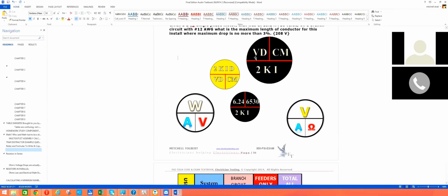But at any rate, anytime you get to plug in something for a voltage drop, either on this yellow circle or over the black circle, either one is going to be that same table, unless that's the value you're actually looking for in the beginning. So I want to multiply these two numbers against each other, and then on the bottom, I'm going to have 2 times 12.9, because it didn't tell me one way or the other on copper or aluminum. So I'm just going to do 2 times my constant, which is 12.9 for copper. And then times, now this is a little trickier, because to really do this test question correctly, I need to talk about continuous duty, but I don't want to do it just yet, because it's probably just going to give us a whole other section to get off track with.